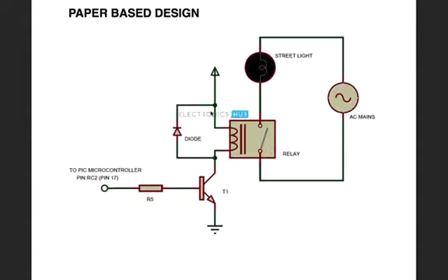When the current time is in the range of the preset time, the light from the outside world is lower and therefore the street light glows. The lights continue to glow at full intensity up to 3 a.m., unless sufficient light comes, like during the daytime. When the time reaches 3 a.m., the intensity of the street light gradually decreases and turns off either at 6 a.m. or whatever we have set in the coding in the Arduino. Hence, auto intensity control of street lights is achieved with the above circuit, which has an LDR, an RTC, a PIC microcontroller and an LED array.